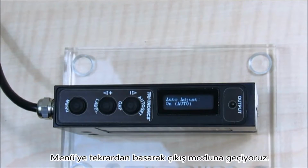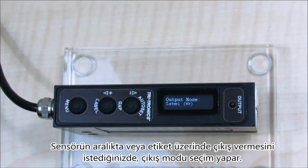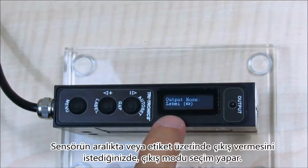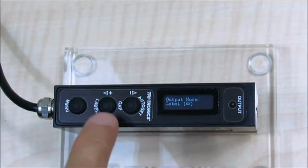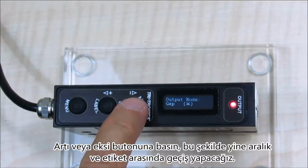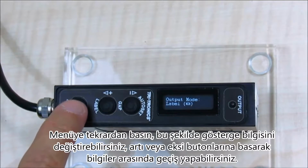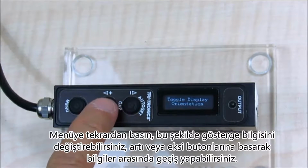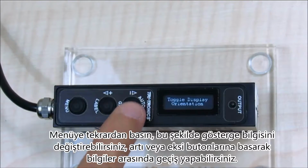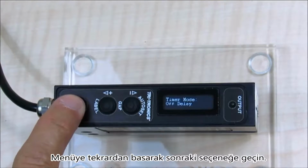Tap Menu again to advance to Output mode. Output mode selects when you want the sensor to give an output, on the gap or on the label. Tapping either the plus or minus button will toggle the setting between gap and label. Tap Menu again and you can change the display orientation. Tap either the plus or the minus button to toggle the orientation. Tap Menu again to advance to the next option.